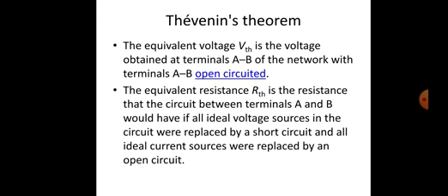In circuit theory terms, the theorem allows any one port network to be reduced to a single voltage source and a single impedance. The theorem also applies to frequency domain AC circuits consisting of reactive, inductive and capacitive and resistive impedance.